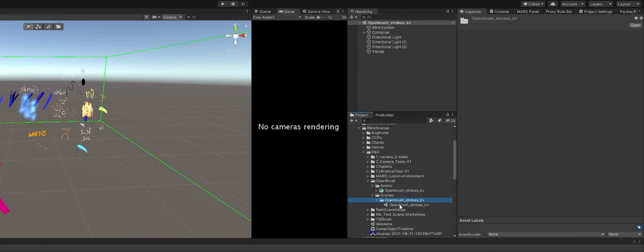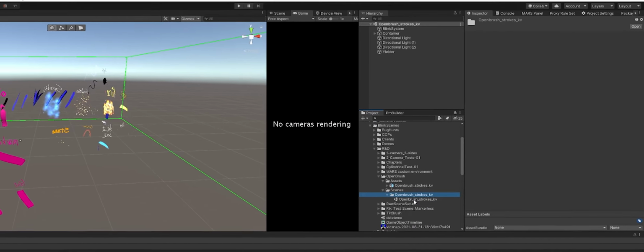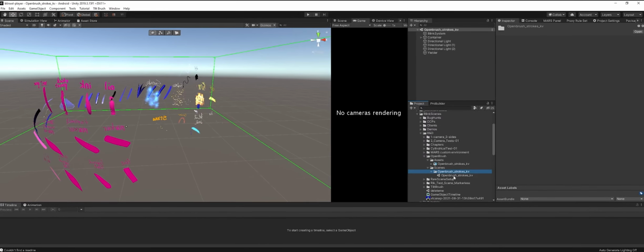It also means that the output file contains the same name as the scene, which is a handy way to keep track of everything. And finally, I make sure that I never put any spaces in any of the scene names, or folder names for that matter. Spaces mess with various internet protocols, and it's just generally bad practice. So don't use spaces. Use underscores or capital letters if you need to have more than one word. But don't use spaces. Very, very bad.